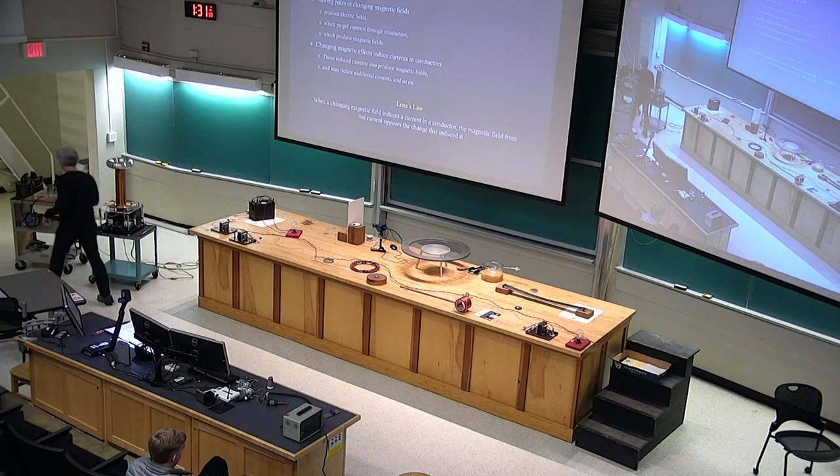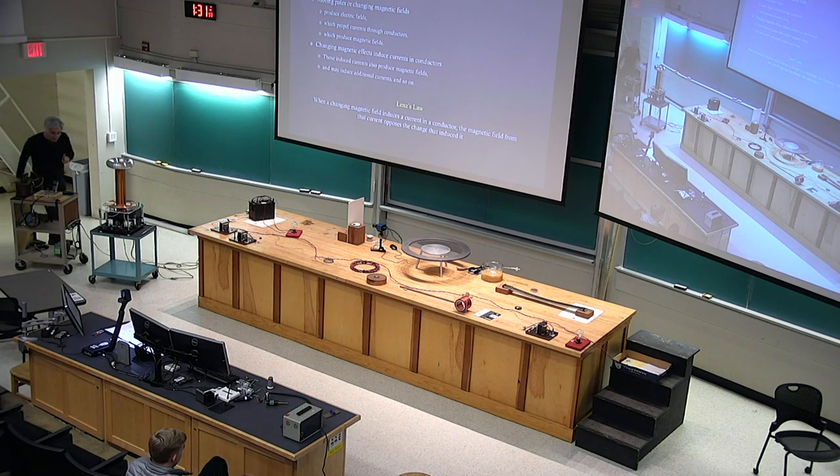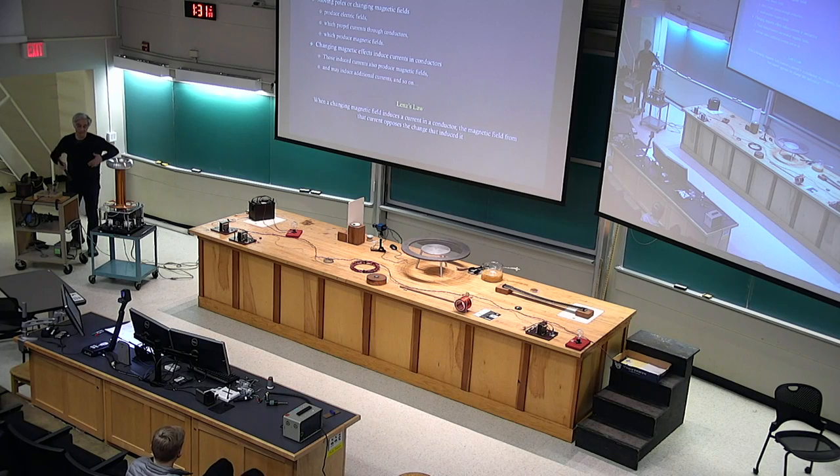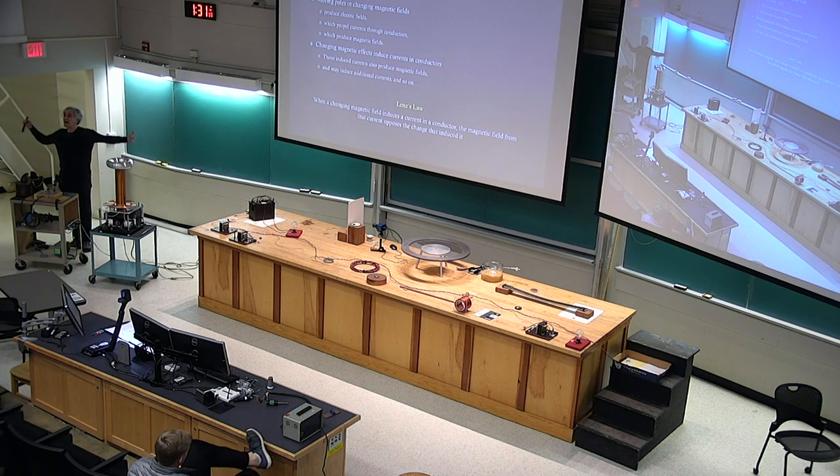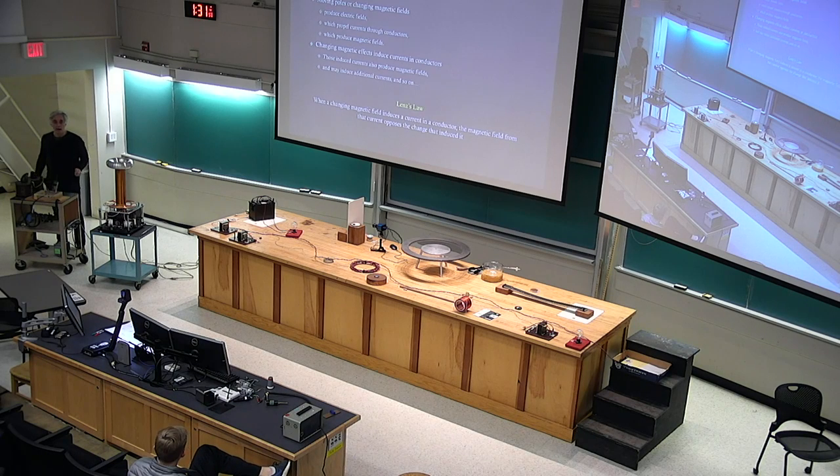The other thing to go back to, I promised that I would come back, and that is when you start the current. Right now with no current in the wires, this is an electromagnet with no current, it's nothing, it's a non-magnet. Boring, boring, boring. But when you start the current, it flows around that coil, and the magnetic field begins to build up in this. It's an electromagnet. It does not become fully magnetic, the whole 9 yards, instantly. It takes time. Why? Because magnetic fields contain energy.